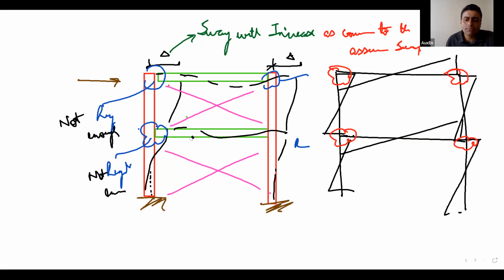Rajenji is saying that fixed support will experience more movement. Right. So because these were not able to take it, the movements will transfer to the support at the bottom. Even your bottom support, you had assumed a certain level of fixity, but if your bottom support is not able to provide a certain level of fixity, again, it will lead to increased sways, correct?